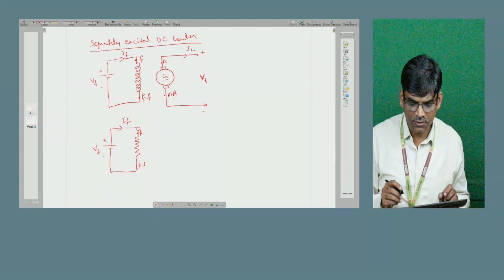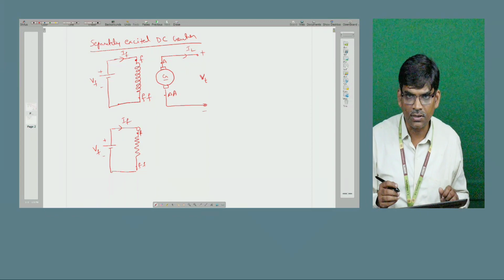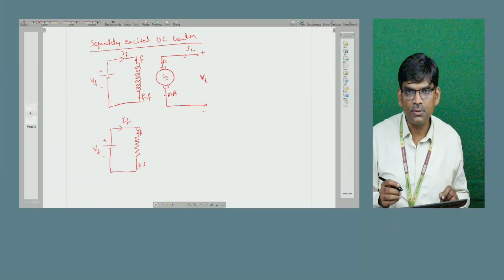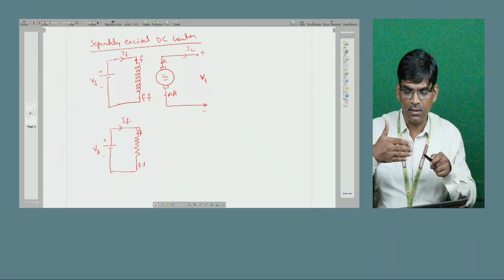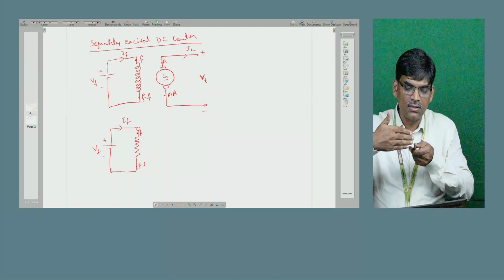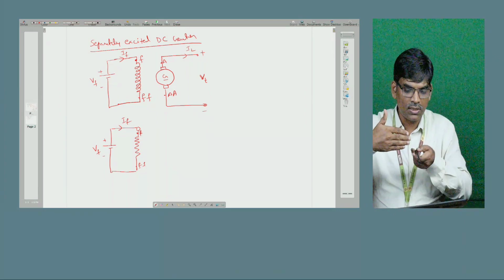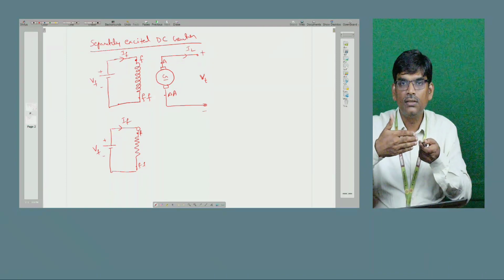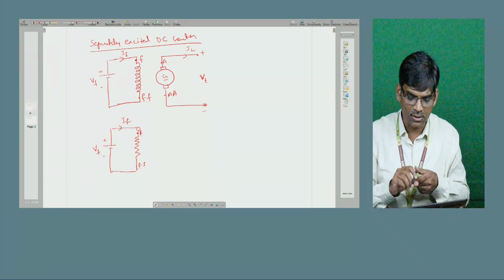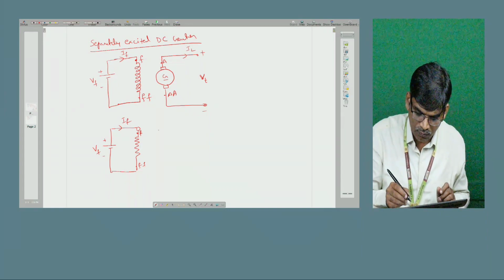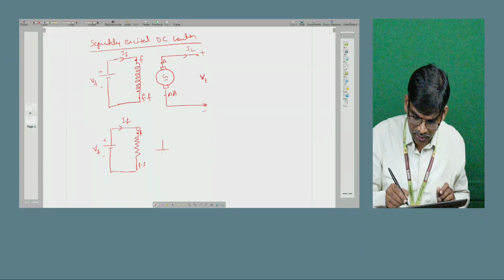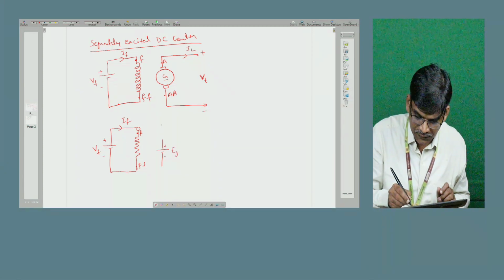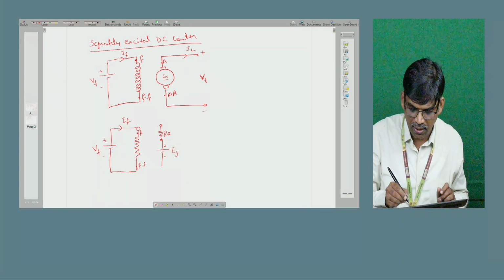After combination, it offers some resistance. Also, this is the magnetic flux. The armature conductor is rotating like this and cuts the magnetic flux. At that time in the entire armature winding, it develops a voltage. That voltage is called the induced voltage, simply denoted by EG. The internal resistance of the winding is simply indicated here as RA.